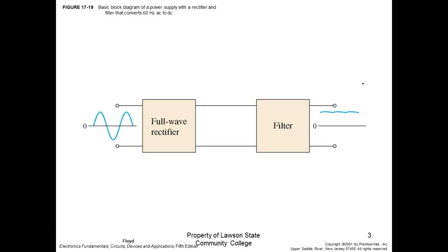So what we do with the capacitor, and by the way, as soon as you add the filter, so originally we came over here, and this guy here, if it's full wave, it gave us this right here, right? And that's where we use that formula, DC is equal to 2V peak over pi.